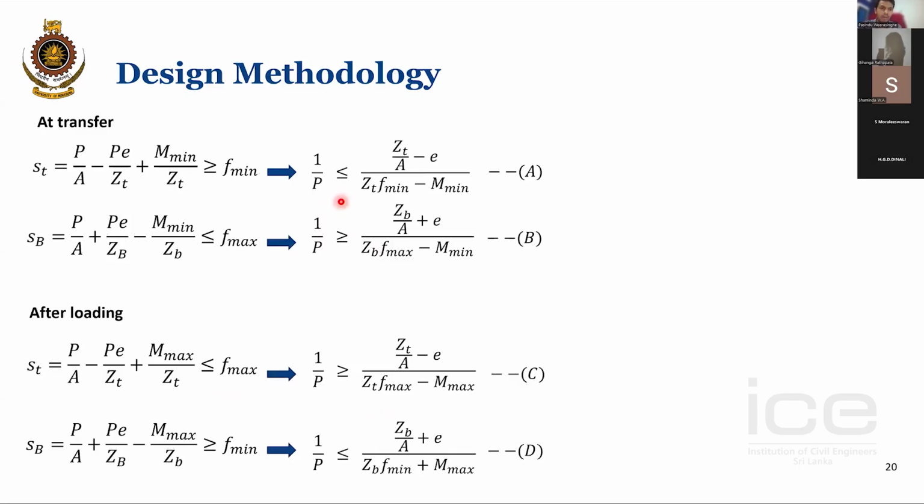So now I have two inequalities at transfer considering the stress at the top and the bottom part, and two inequalities after loading considering the stress at the top and bottom part. And you have different signs, one is less than, greater than, less than. So if I plot these curves